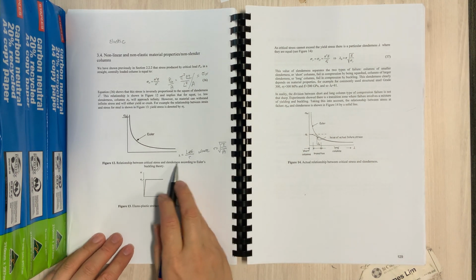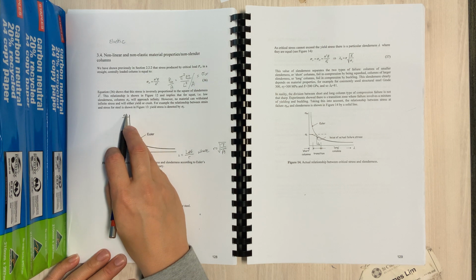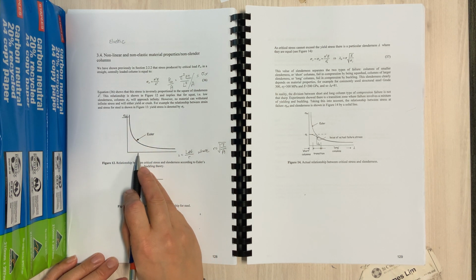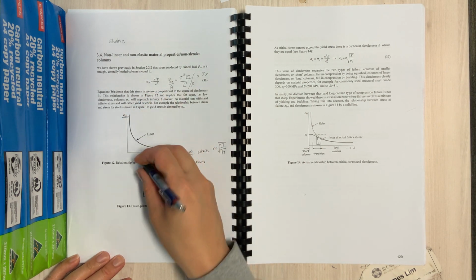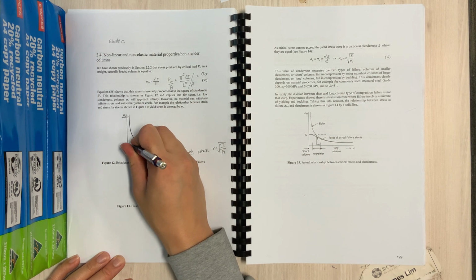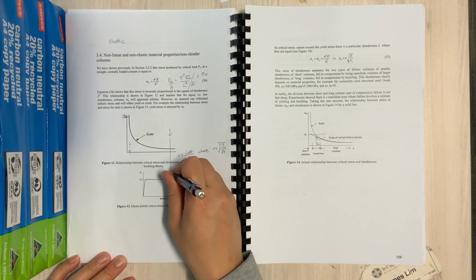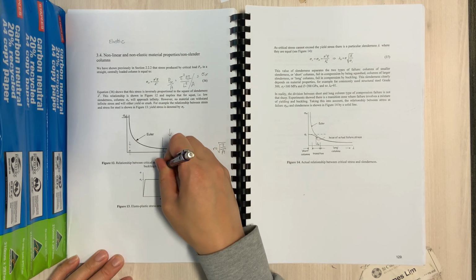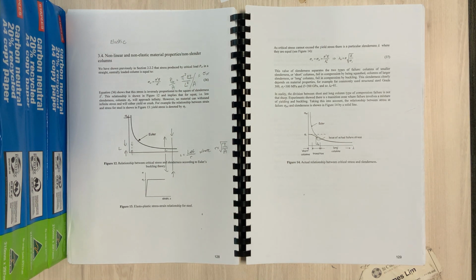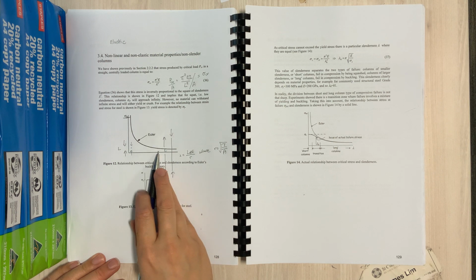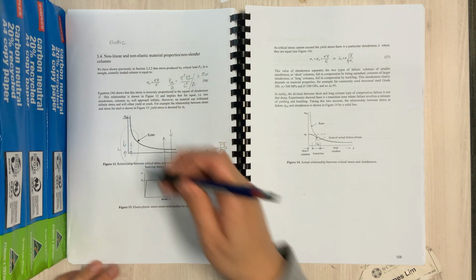Okay, so I normally just think in terms of lambda being the same as L, at least how I think about it. You've got a graph here of the critical stress on the y-axis, and an axis here which represents the length of your structure. When you're in this region here, the length is going to be very small. And when you're back in this lambda here, when the slenderness is large, the length of your specimen is going to be very long, at least compared to when the slenderness is low. So when an engineer says it's got high slenderness, they mean you're in this region of the graph, and when they say it's very stocky or has very low slenderness, you know you're in this region of the graph here.